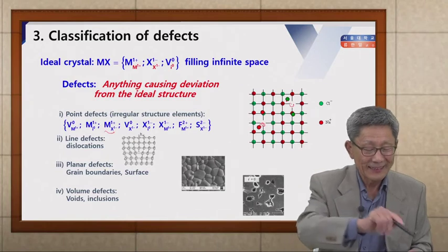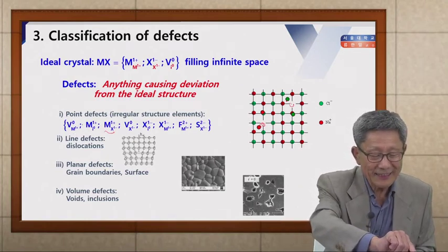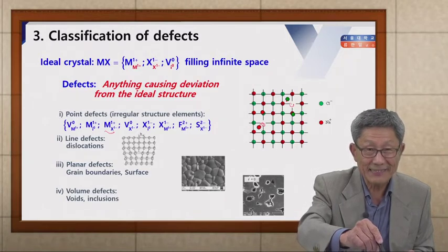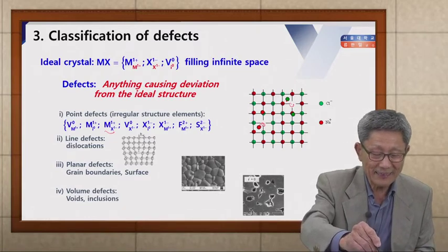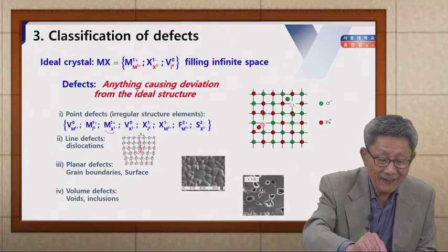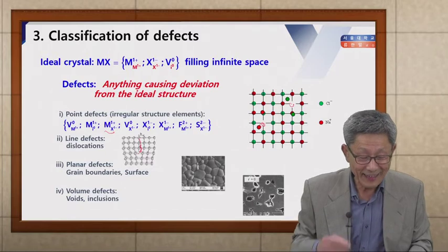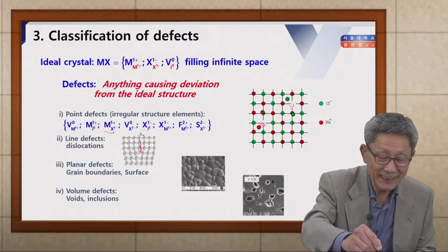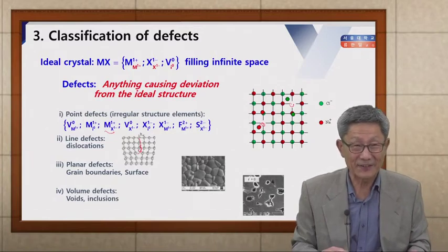Now, suppose that this interstitial defect lined up to make an extra plane in the real lattice. Then this makes an additional plane here. Then you can see the end of this additional plane. This makes a dislocation. And now you can see all the lineup of these atoms. So this is called a line defect.